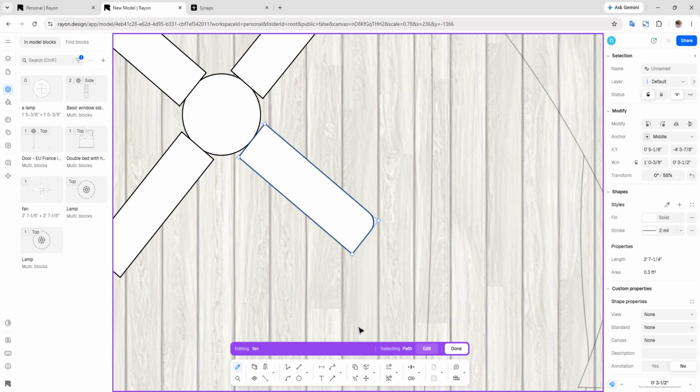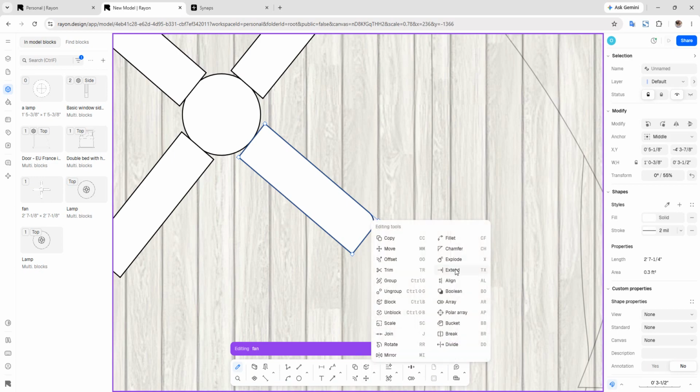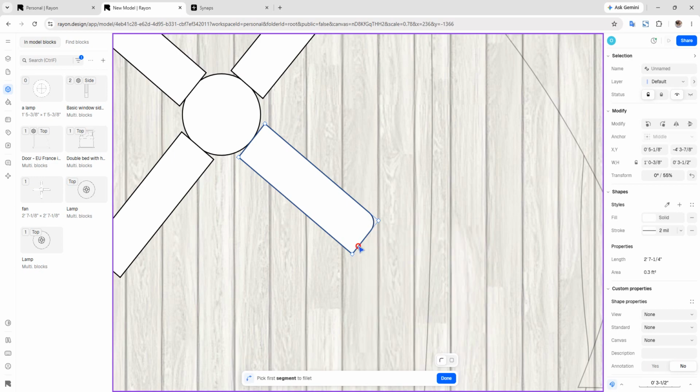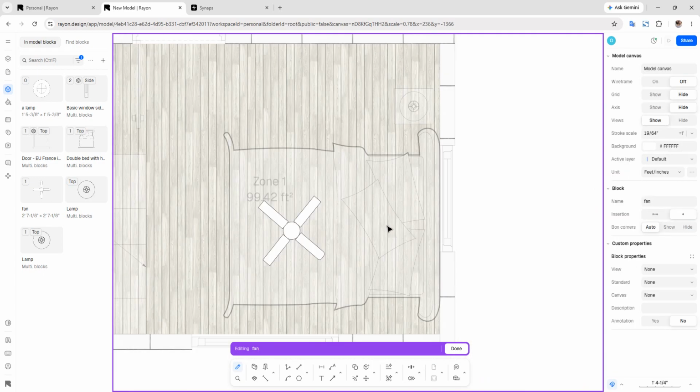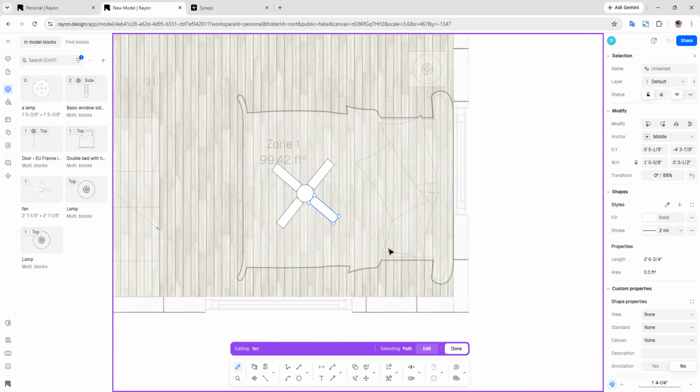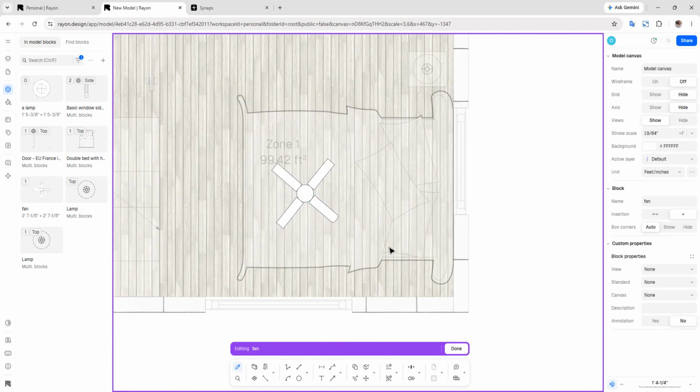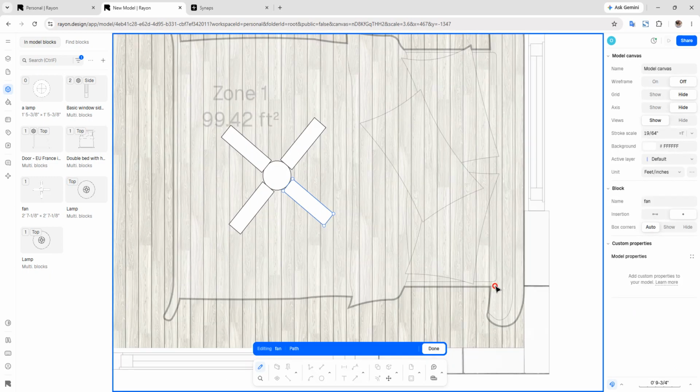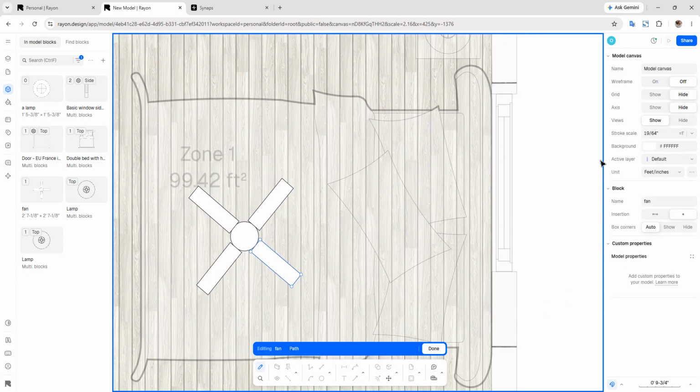Make a radius of that, and again fillet. First segment, second segment. Make a radius of 1 inch. Shift enter. So I can copy it, but anyway I don't want to do that. Control Z for now, as the block was set before.